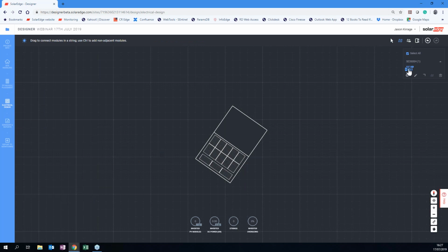And now we've got the inverter up here. We've got the optimizers up here. So we can click on this and it's telling us we can have P300s, we could have P370s, P404s, or P405s. So we can change the optimizer. We'll change them to P404s, okay?